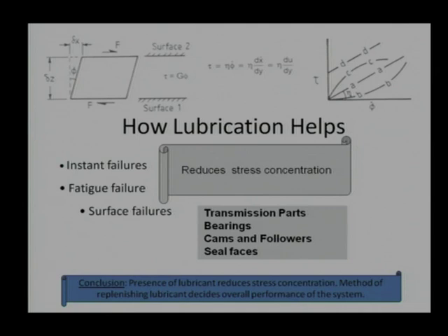It is not only the first sight you provide a lubricant and you will say that lubricant will remain there forever. We know shear stress, lubricant reduces shear stress, but along with the shearing this lubricant also will be wiped out. Once it is wiped out, then again shear stress will increase, or more force will be required. So, that is why we require again and again to replenish the lubricant at the interface. That is important, that is why the lubrication mechanisms are important.